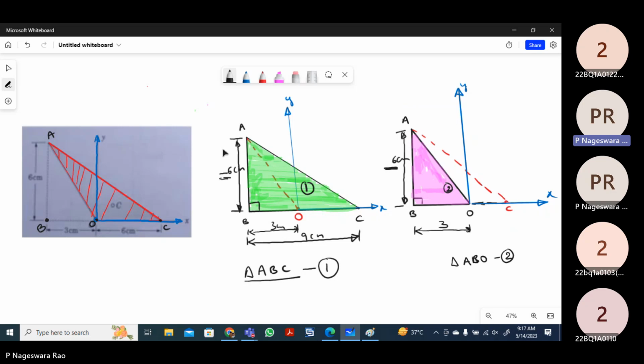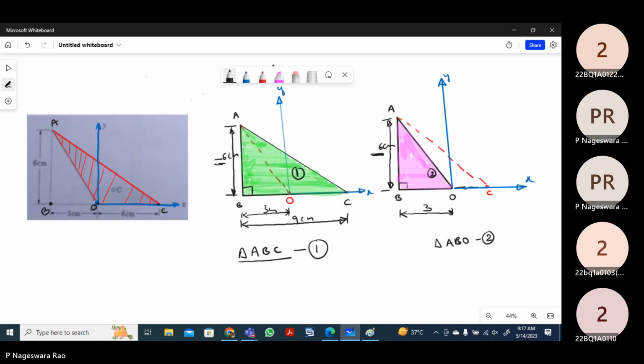First, calculate as usual and write the coordinates. Assume that for this right angle triangle, we don't know exactly where the centroid is. So for the entire triangle ABC, the centroid of the first area is somewhere, call it C1. From the formula, measured from the 90 degree corner, it is one third of the length. If this is 9 centimeters, the distance will be 9 by 3.